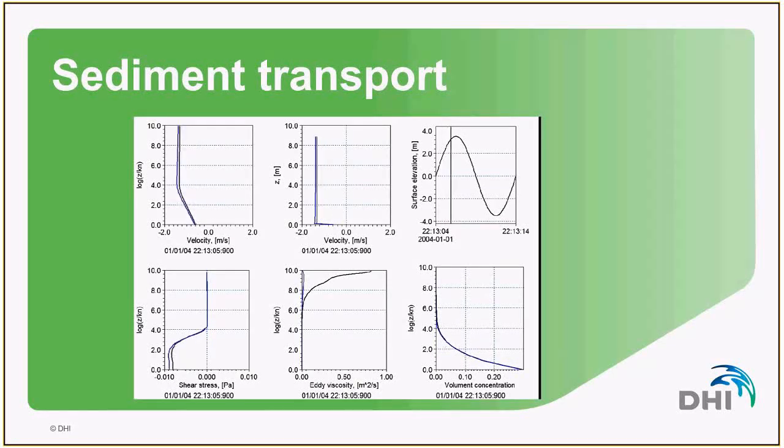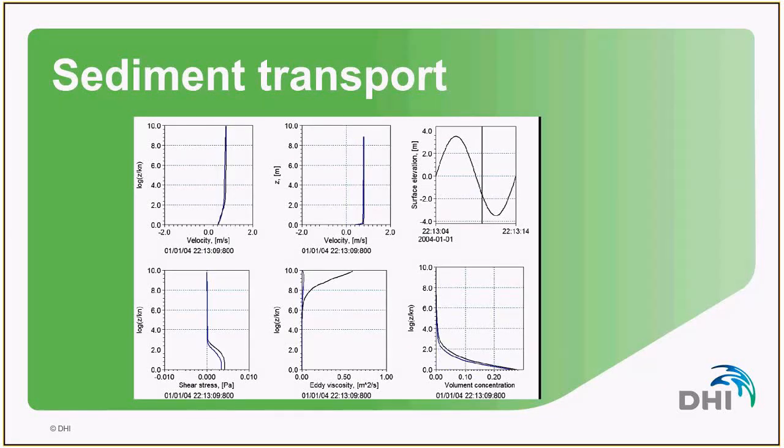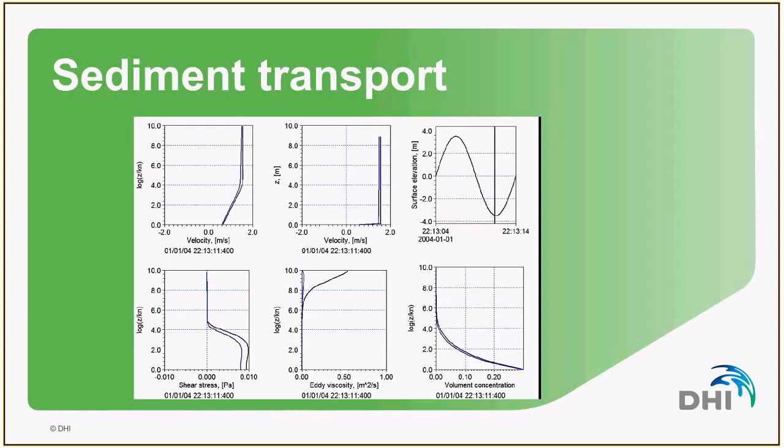So now we have waves, we have currents. Let's have a look at the basic concepts of sediment transport. Here is a quick animation of how the sediments are mobilized by waves and currents over a wave period. And we will have a look at how we can calculate the sediment transport rates.